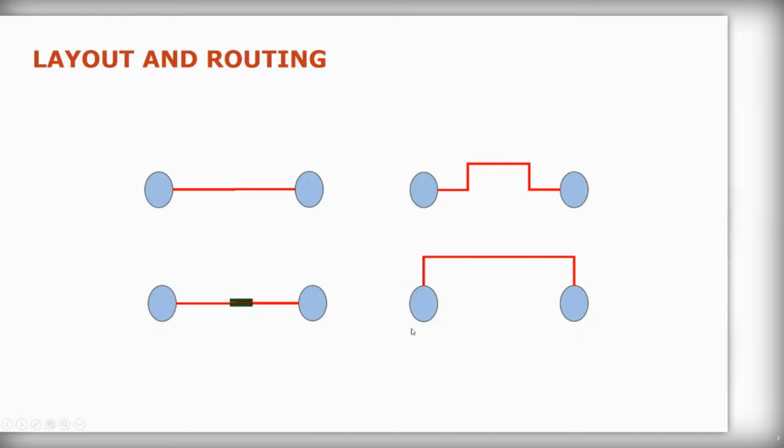Another thing you can consider, rather than simply putting expansion loops for themselves, is to route it differently. Orient your pressure vessel nozzles so that they already have some movement. And as I say, those legs here will be your absorbing legs, and then you need to be proportional to the amount of expansion in this long beam. And that's something you can work out.